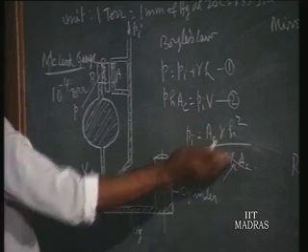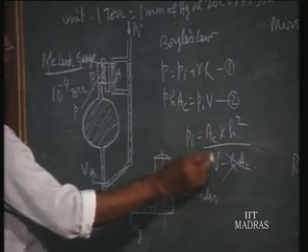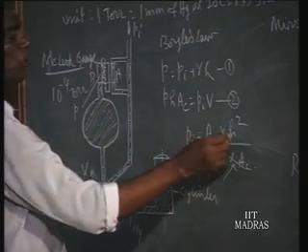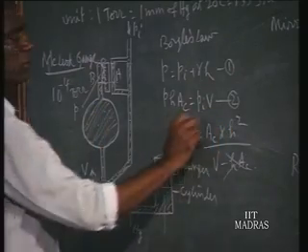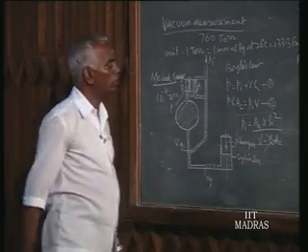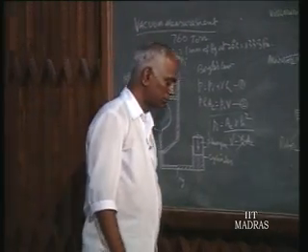So now Pi is obtained here by measuring height. All the other terms are constants given by the manufacturer. By measuring height and substituting in this equation, you get Pi. So this is the principle of measurement. This device is used up to 10 to the power of -4 torr. That is the unknown vacuum pressure; we can calculate the vacuum pressure there.